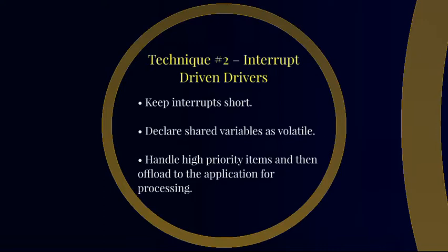The use of interrupts can introduce the need to follow a whole additional set of best practices. For example, it's good practice to keep the interrupts short, declare shared variables as volatile, handle high priority items, and then offload to the application for processing.